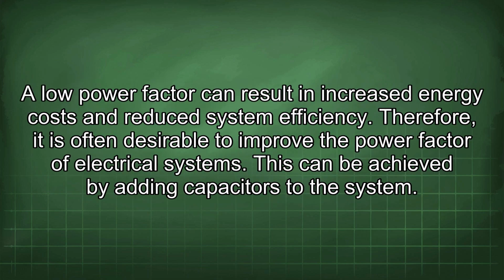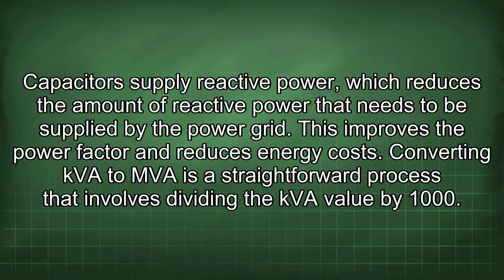A low power factor can result in increased energy costs and reduced system efficiency. Therefore, it is often desirable to improve the power factor of electrical systems. This can be achieved by adding capacitors to the system. Capacitors supply reactive power, which reduces the amount of reactive power that needs to be supplied by the power grid. This improves the power factor and reduces energy cost.